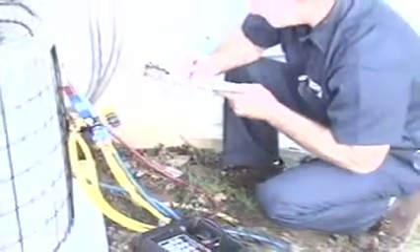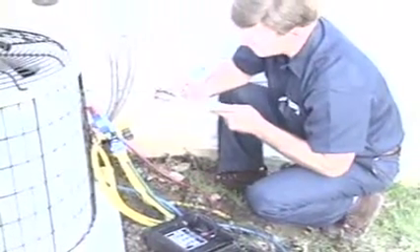Now plug these numbers into the formula. The actual superheat is 13 degrees. Record the superheat on the invoice for future reference. It's important to understand that the amount of superheat will vary depending upon the conditions under which the system is operating. Okay, now the next thing to calculate is the amount of subcooling.